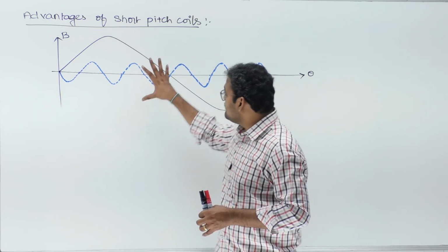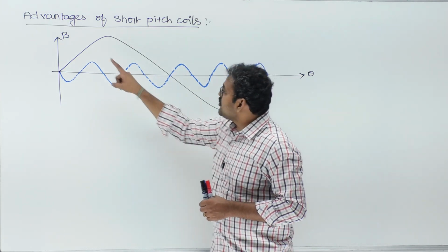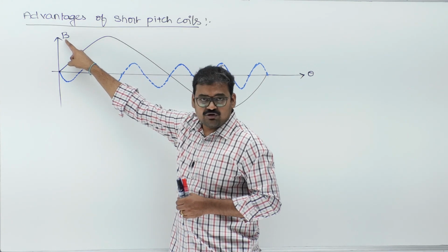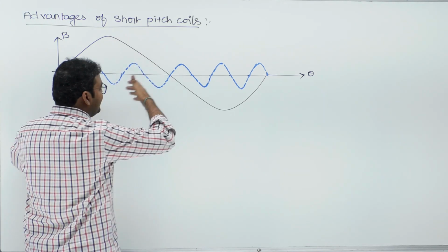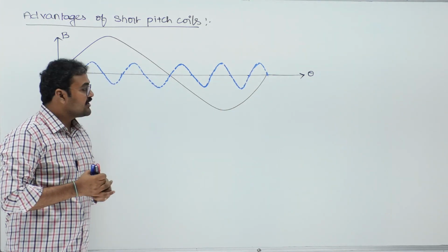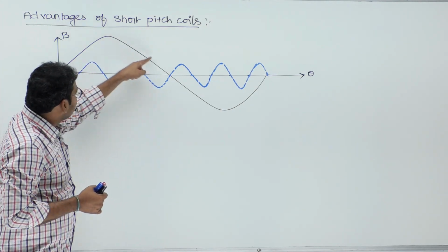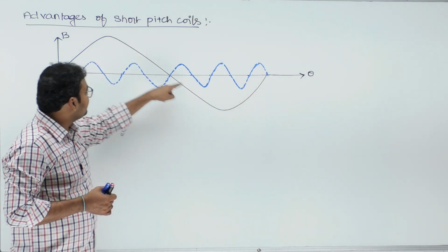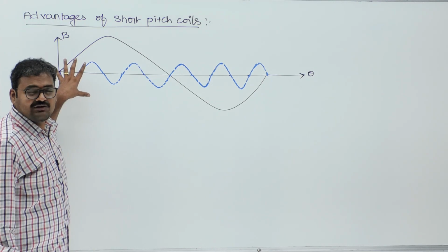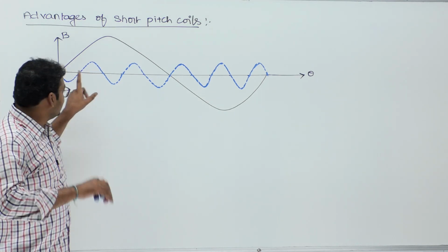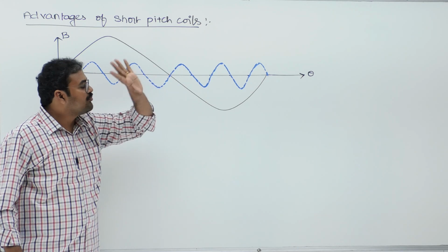That's why I took a simple diagram here. I am drawing a diagram of a flux density waveform with respect to space angle theta, because the magnetic field is spatially distributed. You see, this black color one is the fundamental flux wave. Like that, so many harmonic flux components will also be available. For example, I took a fifth harmonic flux component wave.